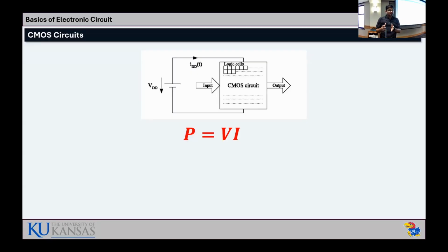But in the second operation, suppose you first performed an AND operation, and then you are doing a multiplication. For multiplication, suppose 70 transistors switch on. So the current flow will be higher, right? So if your current flow is changing here, your power will change, right? So with different instructions running inside your CMOS circuits, the consumption of power is actually changing.